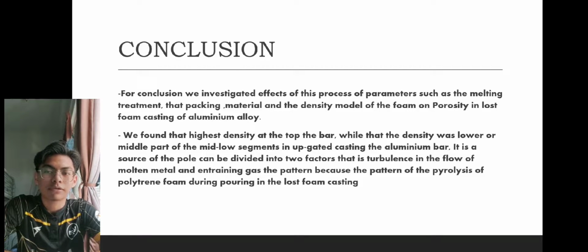We also found the highest density at the top of the bar, while the density was lower in the middle part of the bar in up-gated casting of the aluminium bar. The source of the pores can be divided into two factors, that is turbulence in the flow of molten metal and entraining gas, because of the pyrolysis of the polystyrene foam pattern during pouring in lost foam casting. That's all from us. Thank you.